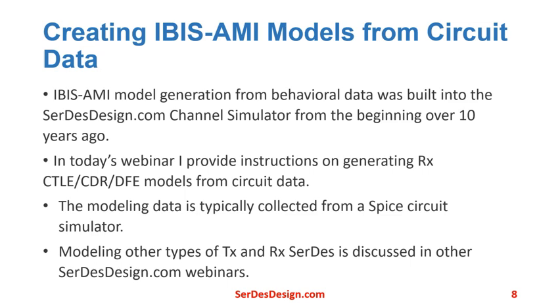Creating IBIS-AMI models from circuit data. IBIS-AMI model generation from behavioral data was built into the SerDesDesign.com channel simulator from the beginning. I've used this process over the past 10 plus years, providing custom IBIS-AMI models to over 40 companies based on the circuit data they provided me. In today's webinar, I provide instructions on generating receiver models with CTLE, CDR, and DFE from circuit data. The modeling data is typically collected from a SPICE circuit simulator. Modeling other types of transmit and receive SerDes is discussed in other SerDesDesign.com webinars.